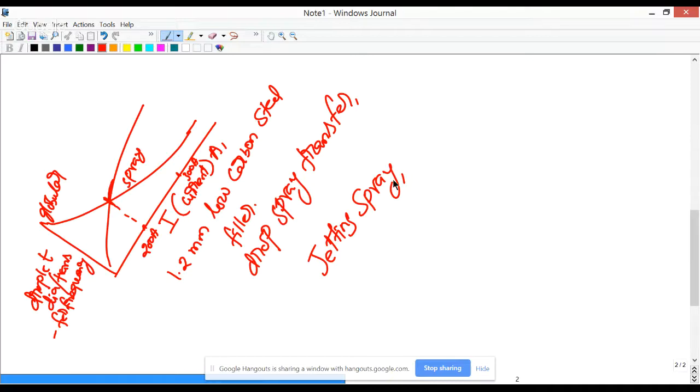And because of continuous detachment of droplets, you have a jetting spray, and the increasing current leads to enormous Lorentz force generation. That could lead to a magnetic field generated in the droplets and the sprays that are detached continuously from the electrode tip. And the enhanced Lorentz force, with the magnetic field developed by this Lorentz force, can lead to a deflection of these sprays continuously in and around